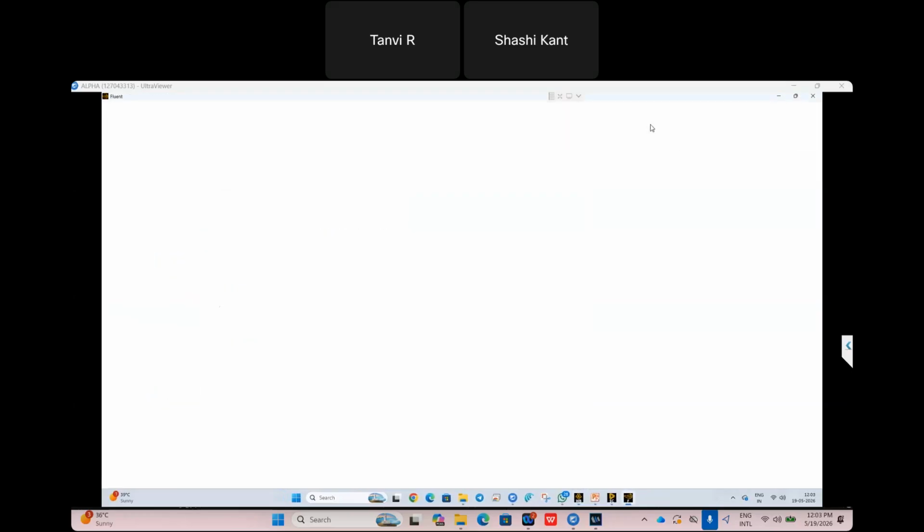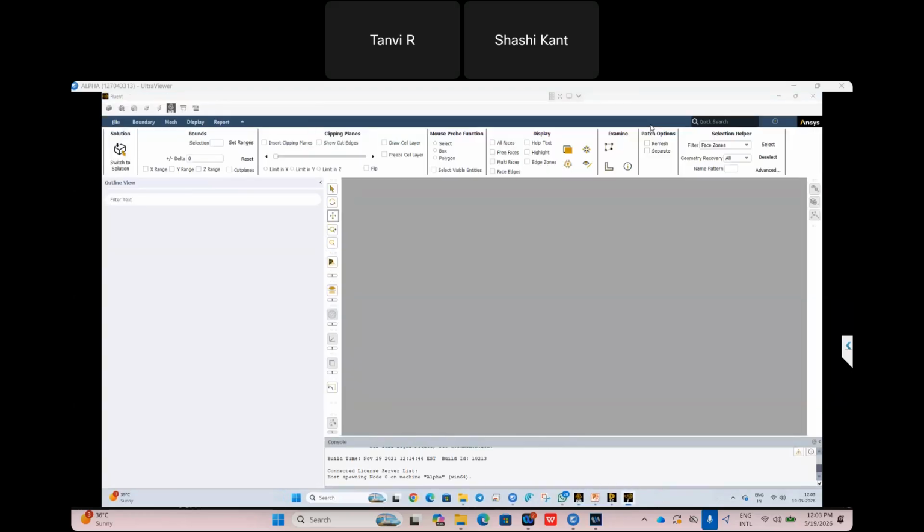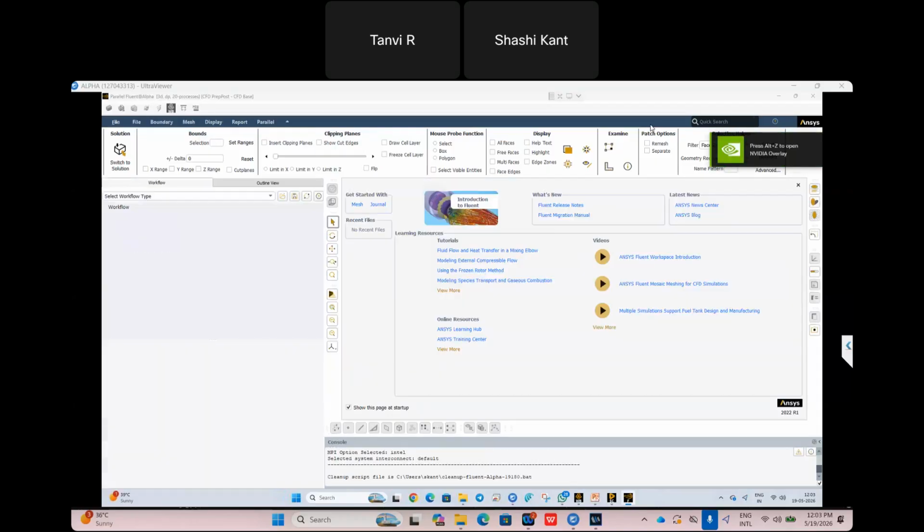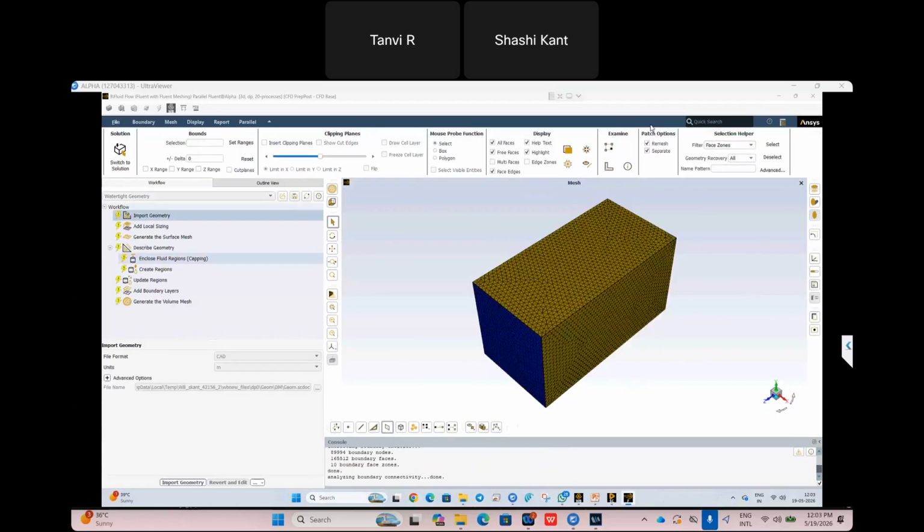That also we can capture. And on the basis of that, we can capture the pressure profile on the body of the eVTOL, the velocity contour surrounding the eVTOL, and also the turbulence intensity on the body. So all of these can be captured very easily. On the basis of all these responses, you can see how we can reduce the drag coefficient.